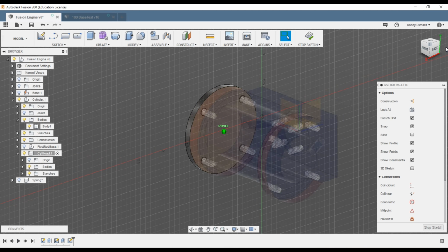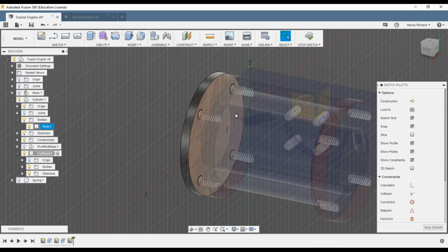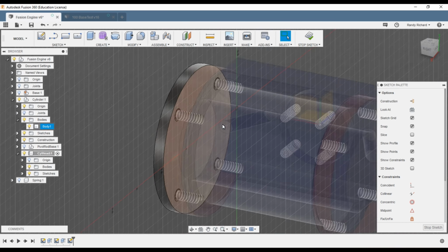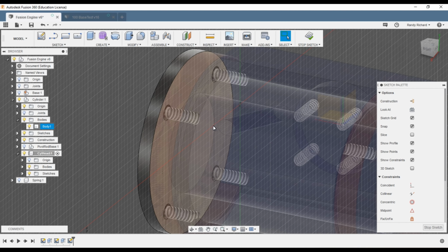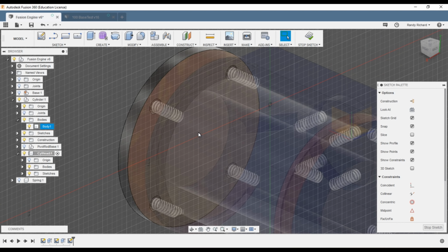All right, so what we want to do is make this projection on the inside from the cylinder head, but it's not very much, it's just enough to help center the head up, and you don't want it to cover the port here, so it's only maybe 30 thousandths or so, but you got to watch out. It's going to affect our piston clearance, so we don't want to come up past the port edge at all, and it's just enough to give it a little centering.